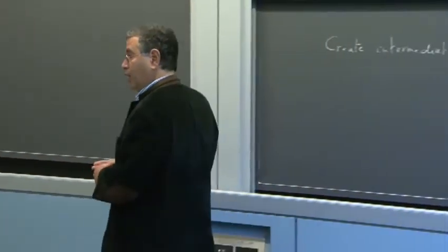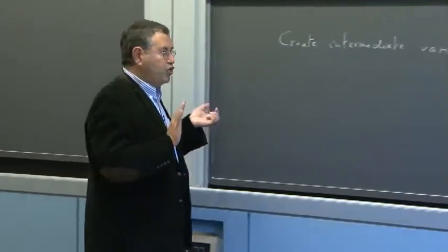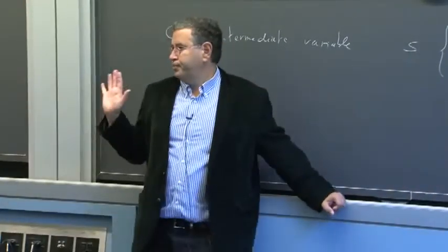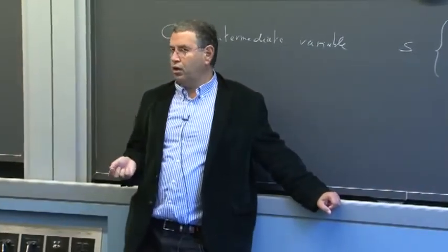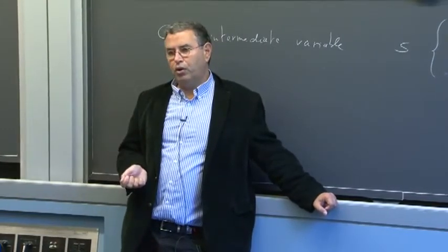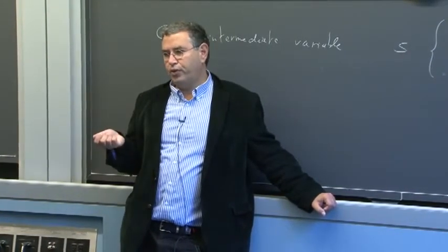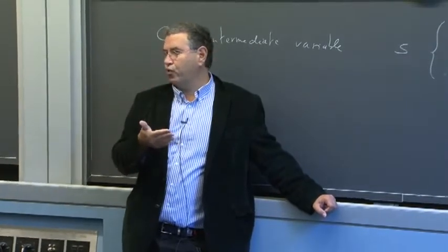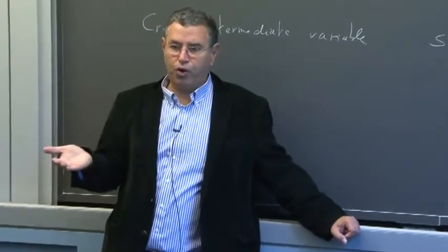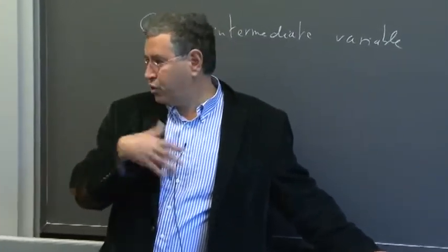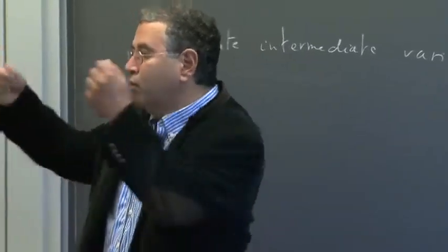All right? So at this point, we're not solving a control problem. We just say, let's make it first order. All right? So we're looking for an intermediate variable that verifies two properties. Instead of an nth order problem, we have a first order problem. But of course, controlling this variable to 0 solves the original nth order problem.